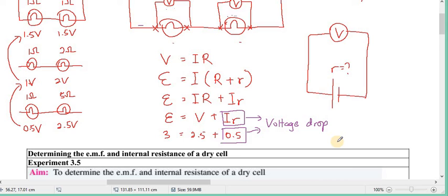But let's say I take this switch, the wire, and I connect to a fan in block D. So far away, block D. If I turn on, do you think the fan in block D can get 220 to 240? Most probably cannot, because too far away. When too far away, the wire is very long, so the resistance in the wire will be very high.